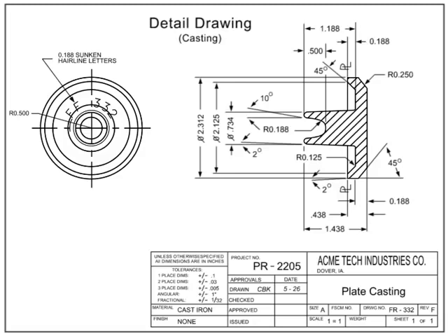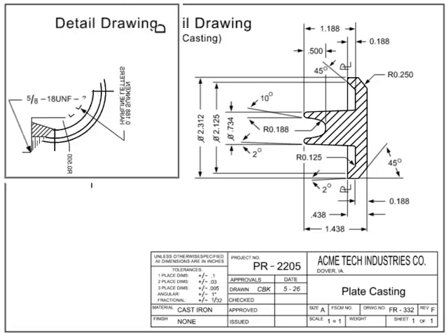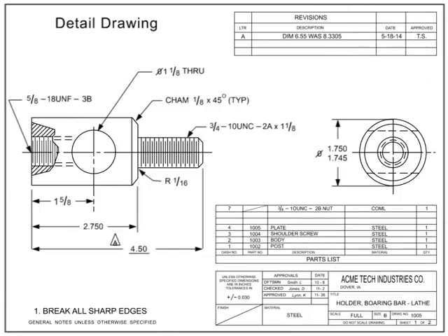Other information that may be included on a casting drawing are mold lines, datum plane references, and even information on how to best remove the part from the mold. A machine drawing details all the information required to take raw material and turn it into a finished part. The machining tolerances, material, finishes, etc. are all shown on the detail drawing.